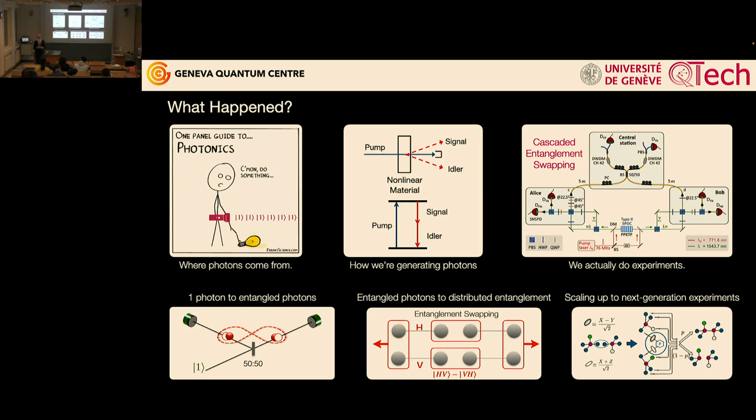That's where the complexity comes in, engineering your source. Even in a bulk material where you're just sending a laser through a bit of glass, which most normally just looks like a bit of glass, you will have some loss. Some materials have more loss, higher index of refraction, more reflections. You can play with your anti-reflection coatings on the end faces. Sometimes we start using circuits or waveguides in these devices. Then you've got to worry about mode matching, laser or fiber mode. This is why a lot of our battle is really loss and coupling. We have one device and we want to marry it to another device. We need to get photons from here to there.